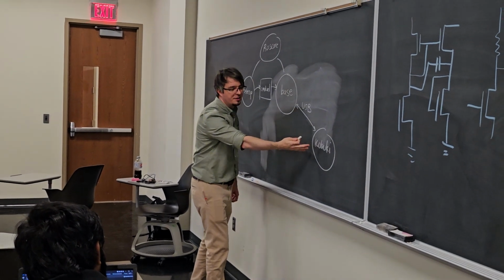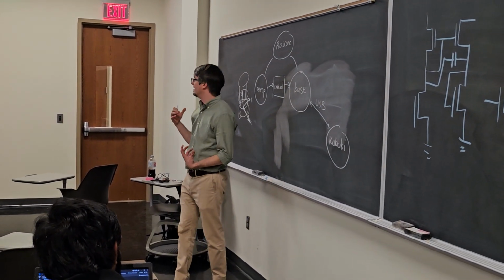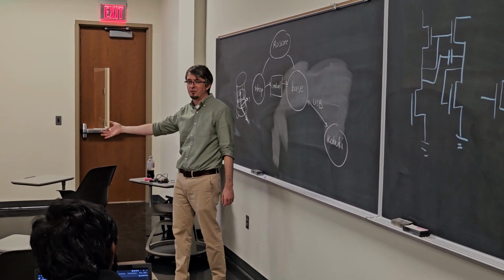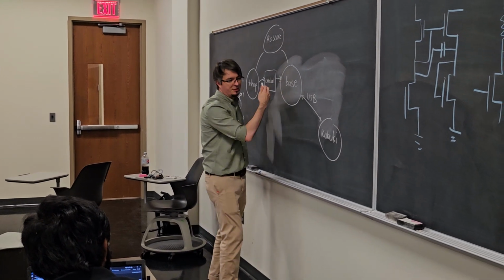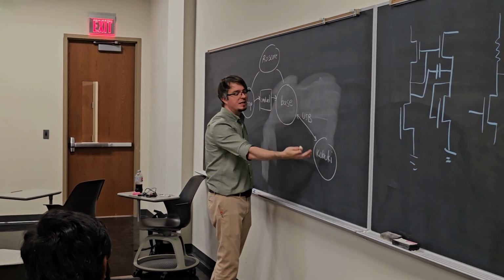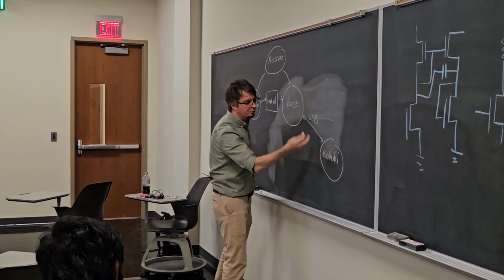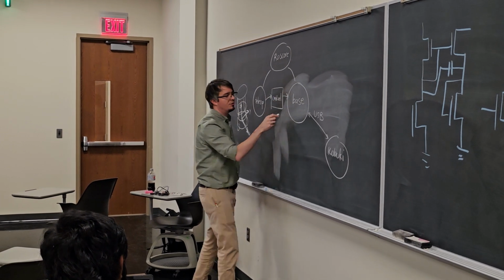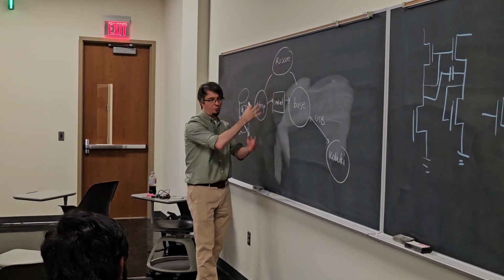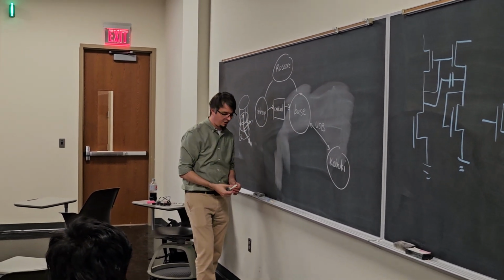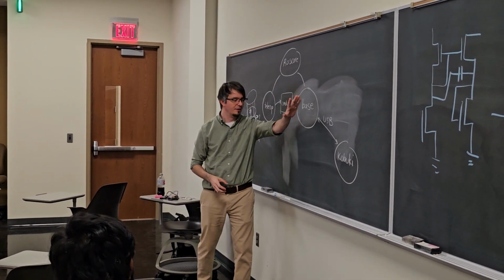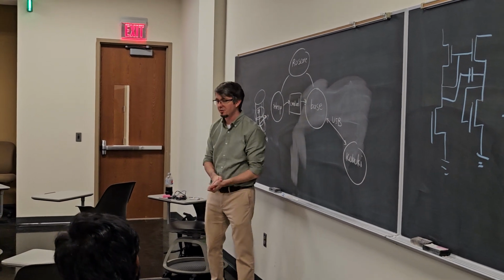And the Kabuki is just its own kind of random robot. It has its own set of commands that it responds to. And this base is managing the commands and reading the sensor information through the Kabuki over USB. The base then publishes that sensory information back to the rest of the ROS network. So this thing's doing its own thing and then providing a ROS interface for everybody else. Got it.